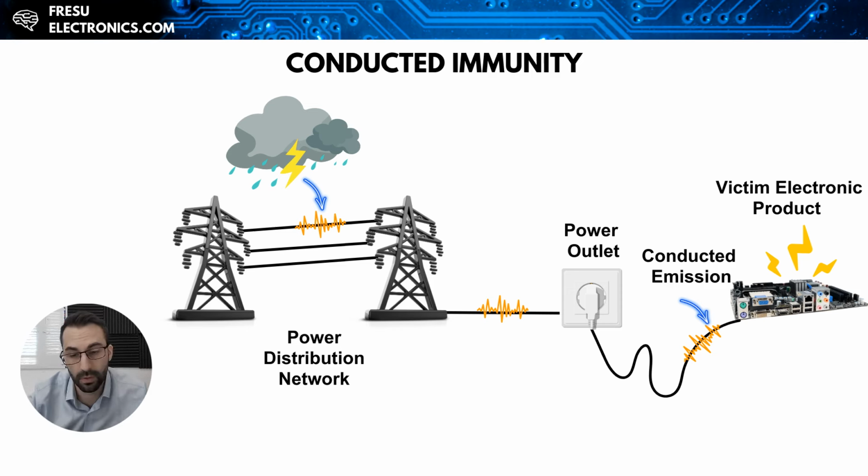One of the most common ways susceptibility or immunity issues arise is through disturbances reaching our system, such as when lightning strikes on the power transmission line which is providing power to the installation. Some of the disturbances may also cause the loss of power for long periods or short outages. In the former case, the system is not expected to maintain operation. However, in the latter case, for example, when the circuit breaker is attempting to reestablish the power, the product is expected to maintain normal operation without the loss of data or its function.